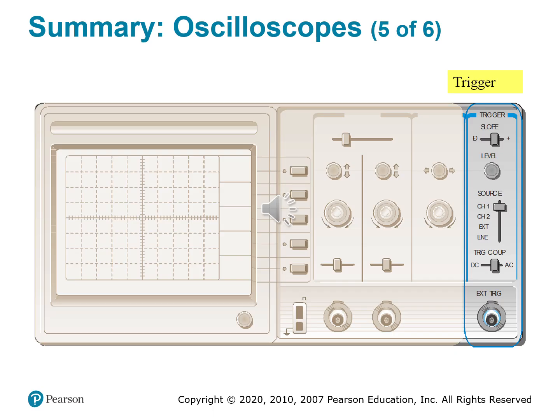Okay, locking it in, the trigger section. So you've seen how to scale voltage and you've seen how to stretch time on the scope. But if your waveform won't stay still on the screen, what's the fix? You'll find that out pretty quickly. Your waveform won't stay on the screen. That's where the trigger section of the oscilloscope comes in.